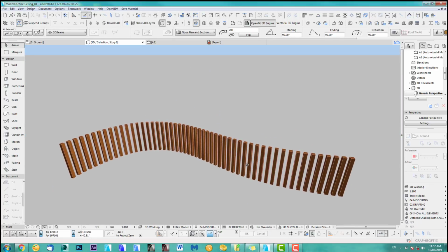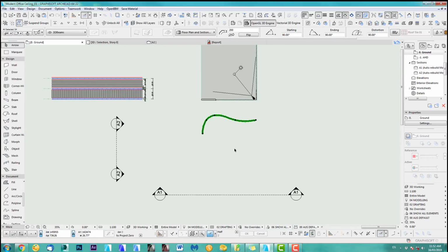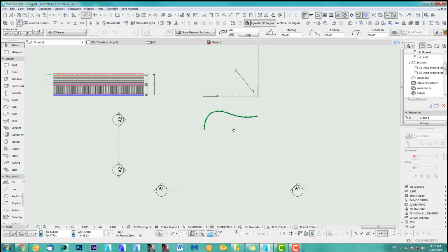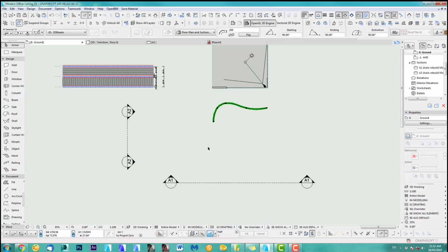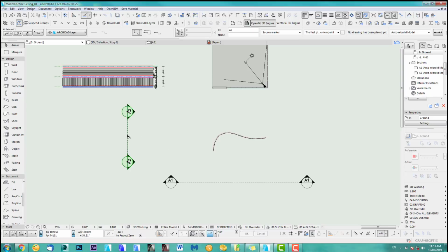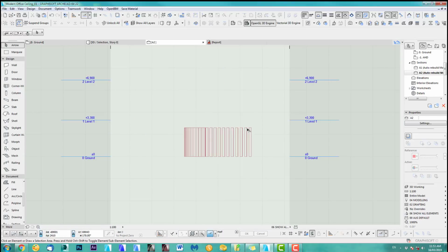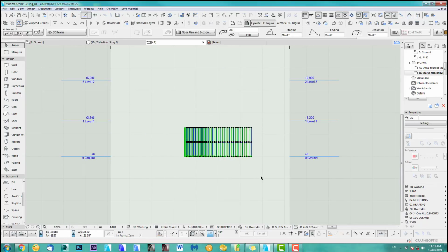That looks great. What I want to do with this now is rotate this, and that's why I use the shell tool and not the wall or the slab, because the shell tool you can rotate in 3D in elevations and sections. So let's move this down. I'm definitely in the view of my elevation, open it. There we go. So we take all this.